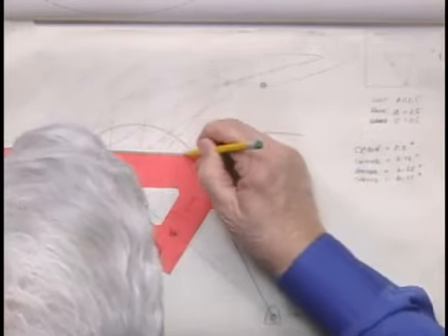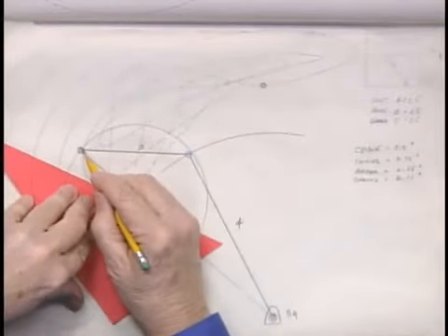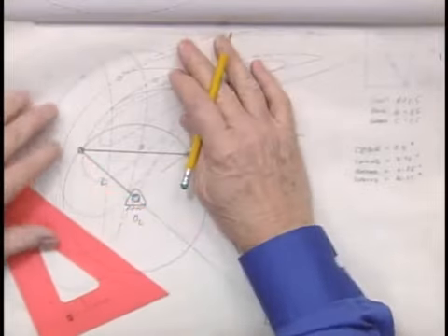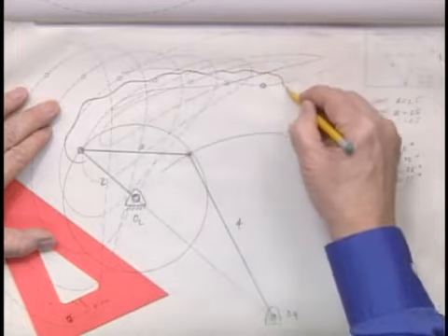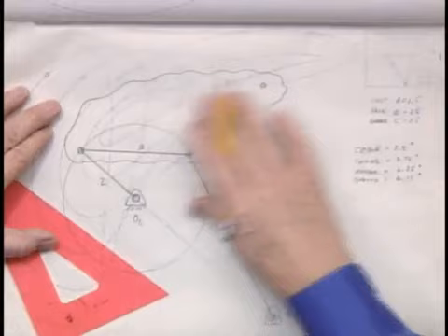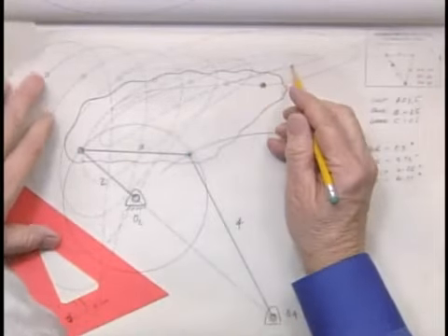And here is link 3. Now this is the line of centers of the coupler. So that's the kinematic coupler, I'll call it. But I want to extend that coupler. I'm going to have to make that coupler include this point out here that generates the curve of interest. And the shape of that can be whatever I feel like. But that's the point of interest.